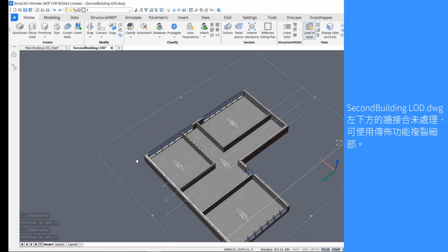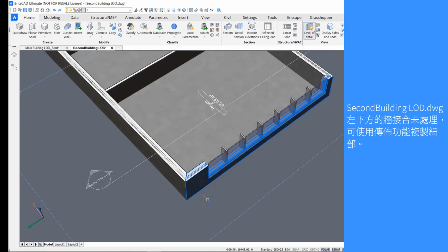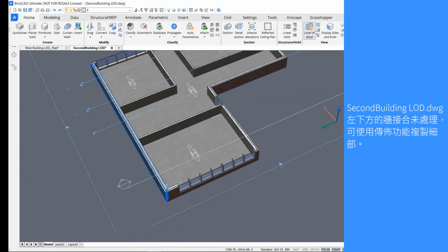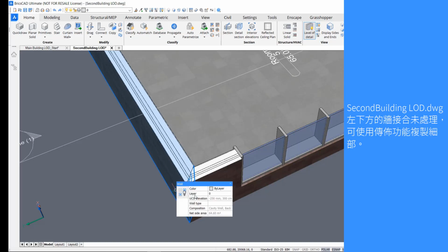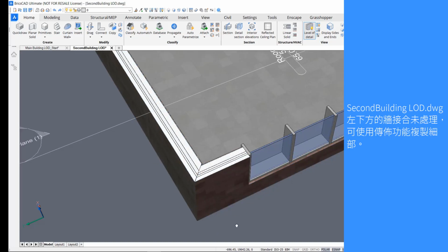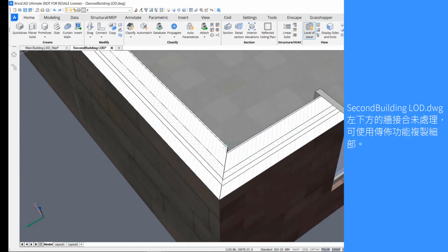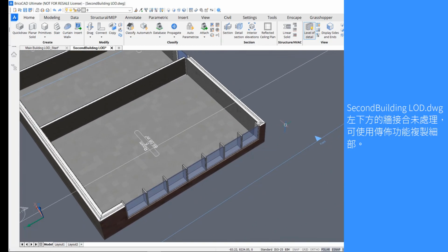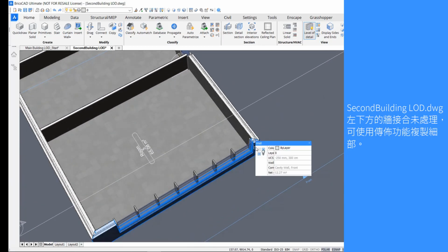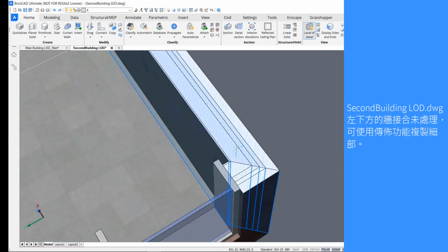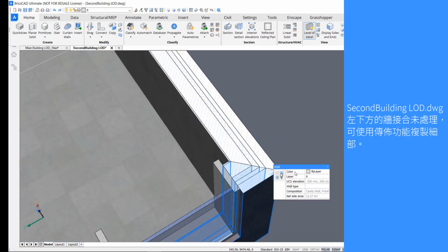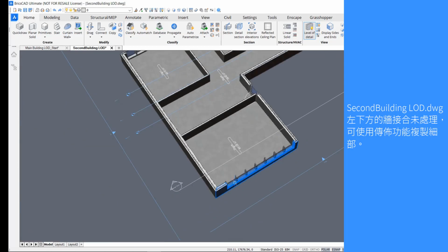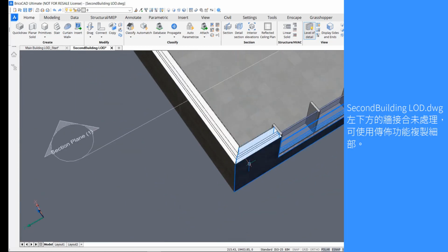And zoom into the front, and zoom into the connection of the wall from the front and the back wall composition. So you can see here it's not perfectly aligned and connected to each other, since the compositions have a different thickness. If we zoom into another wall connection, which has both front composition, you can see these connections look pretty good. It's only this one that we want to change.